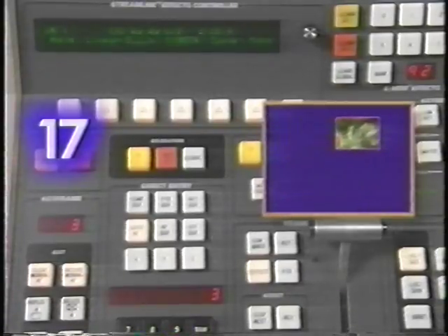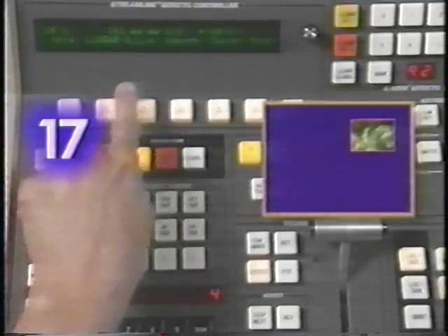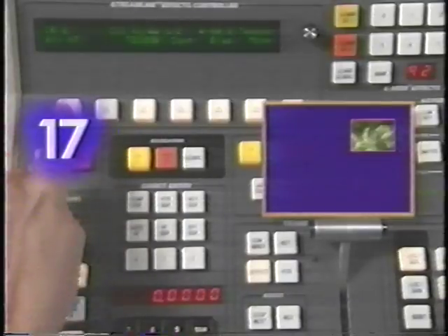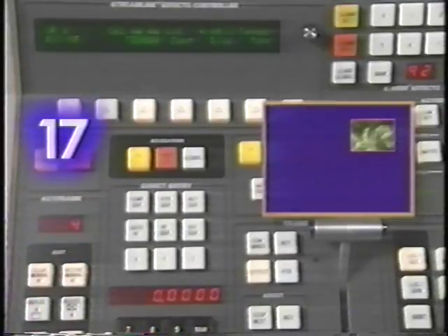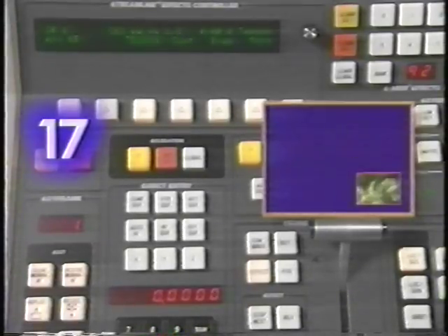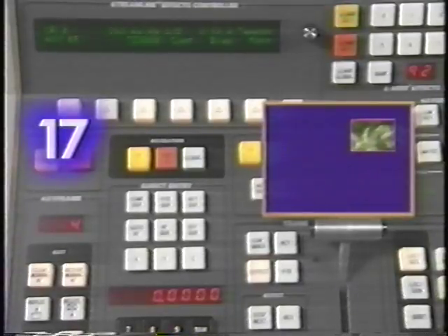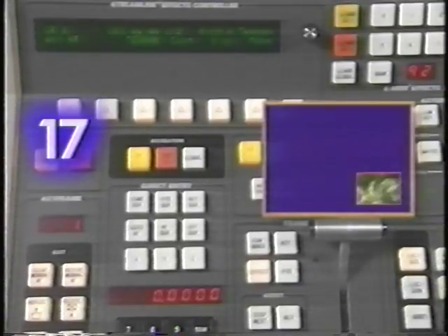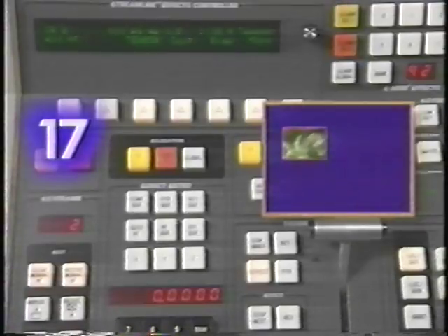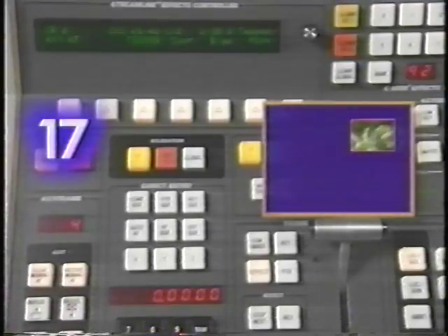With Linear still selected, press All Keyframes in the same menu. This will cause the location and center of orbit parameters to change in a linear fashion for every keyframe in the effect. Rewind and run your effect. Notice that as the effect approaches and leaves each keyframe position, there's an abrupt change in direction, almost as if the picture bounced at the keyframe point.